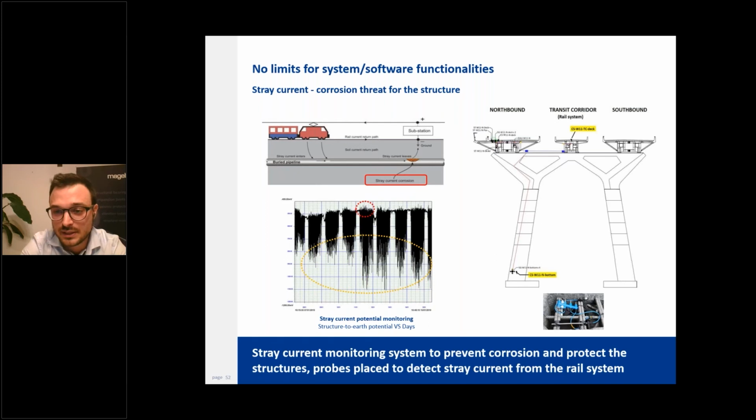In general, these peaks show activity. So a change to either abnormally high or low values indicates that there could be an increase in stray current, so a higher risk of corrosion, that could alert the users to take action to bring these measurements inside the typical working range, so they can protect the structure before corrosion starts.